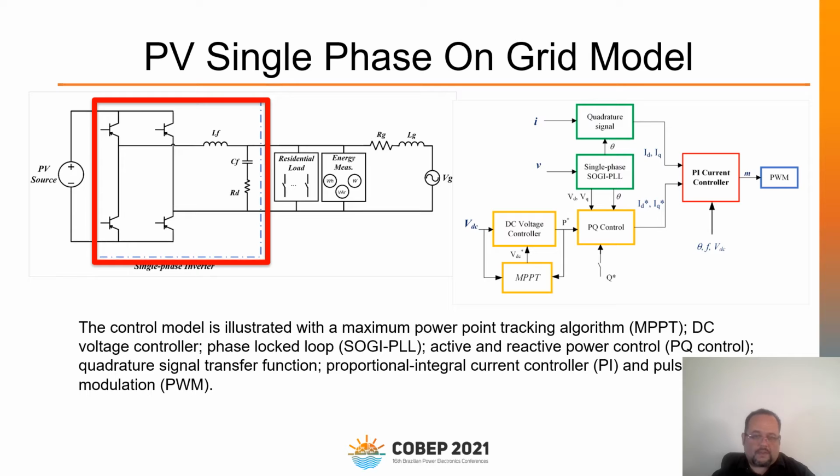The control model is illustrated with a maximum power point tracking algorithm, MPPT, DC voltage controller, phase locked loop, SOGI, active and reactive power control, PQ control, quadrature signal transfer function, proportional integral current controller, and pulse width modulation, PWM.